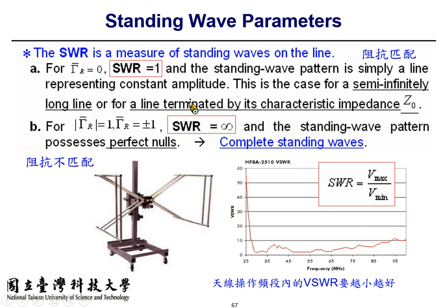And the antenna shown here is of certain size. What kind of size? Can you get an estimation about it? What is the wavelength of a 100 megahertz signal? Well, it's 3 meters. What is the wavelength of 30 megahertz? That's 10 meters.